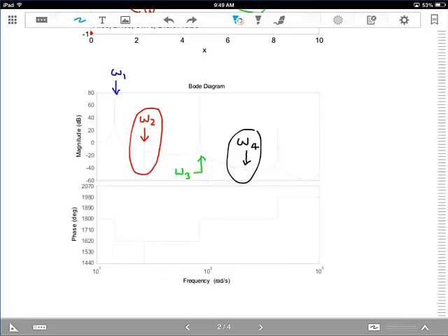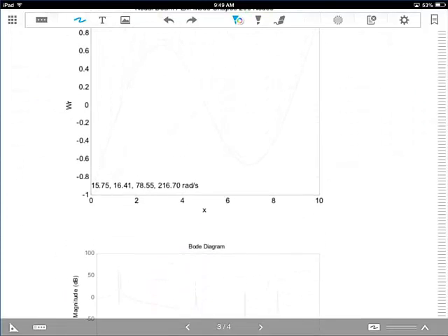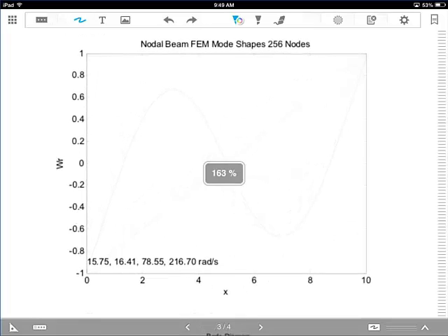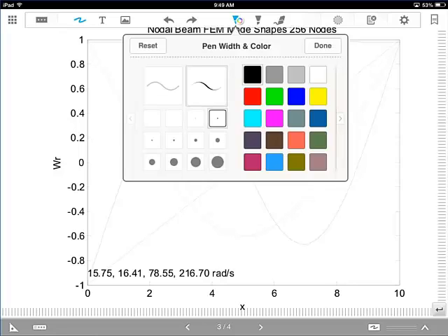So let's see what happens when you now move to x equal 2 meters. Well, you notice a couple things here. Zoom in a little bit here. First of all, if you compare the natural frequencies, you use the same K stiffness, you'll notice that the first mode is still up here, kind of this rigid mode, but it looks even more rigid.